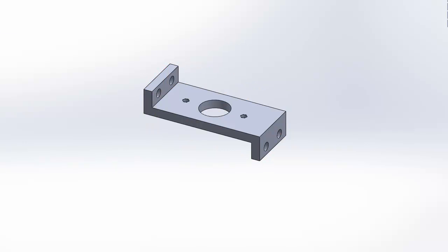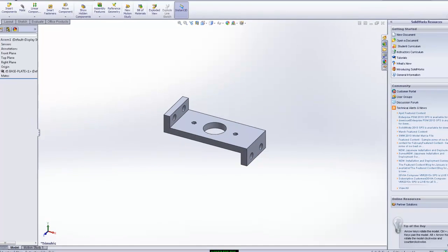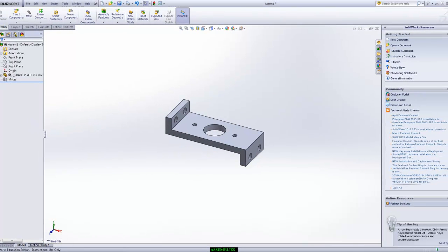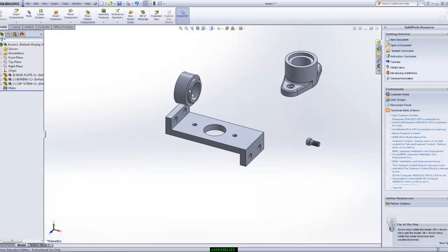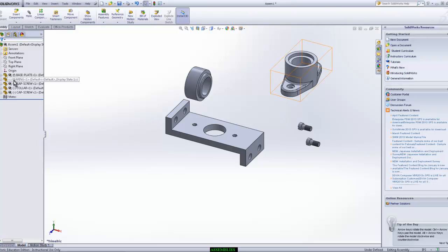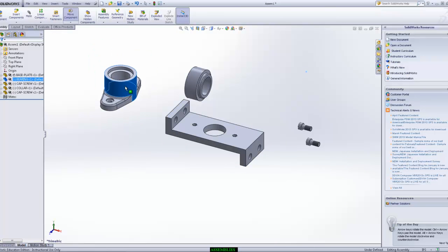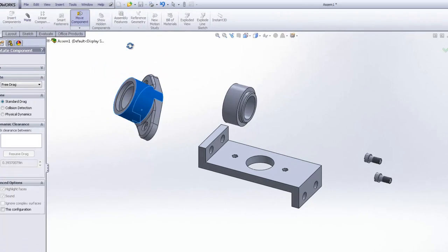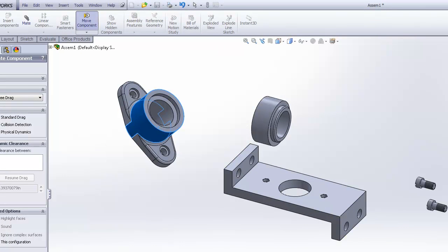The next one I bring in, doesn't really matter what order, drag in the bearing, drag in the cap screw, drag in the collar. Oh, I need 2 cap screws, right? Drag in another one. Okay. Those do not have an F by them. They are floating. I can take those parts and move them anywhere I want, or rotate them any way I want in the environment.